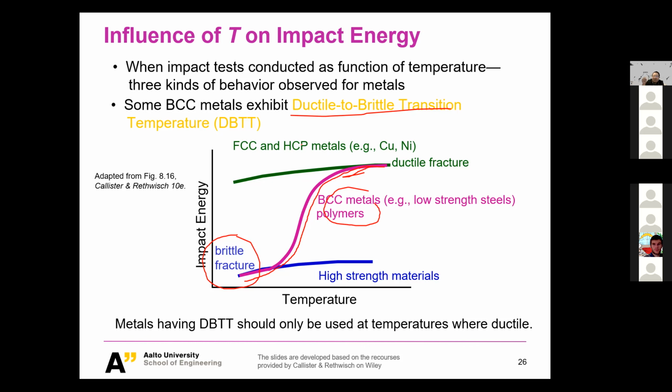When your atoms are close packed, when the slip plane is on the close packing plane, that is somewhat easier. But remember, for the BCC guys, their slip plane is not on the most densely packed plane. It is not 111, but 110 or 112 or so. So the atoms are always a little bit distanced from each other. And that little difference makes the dislocations really hard to move.